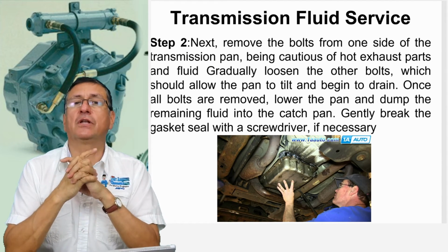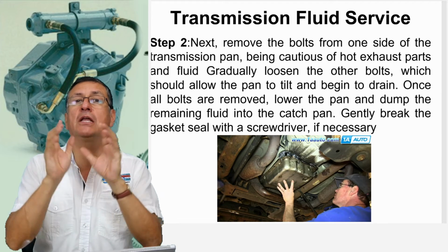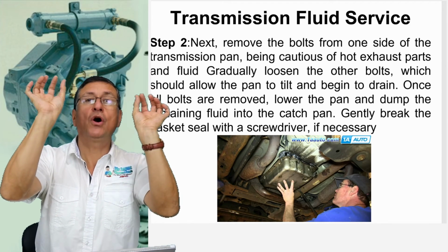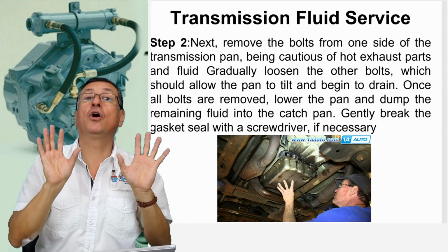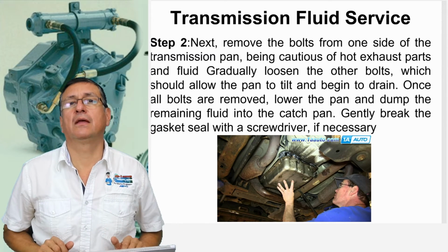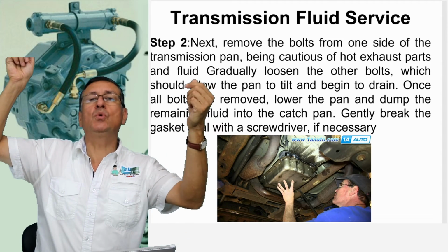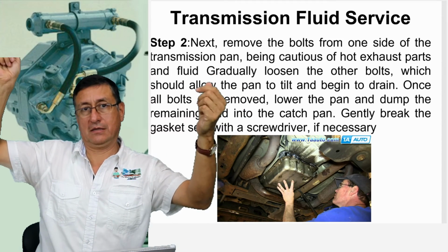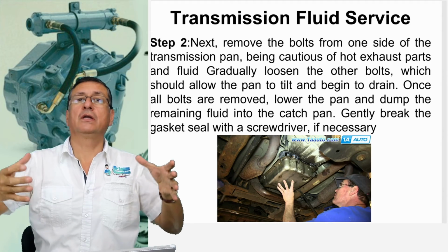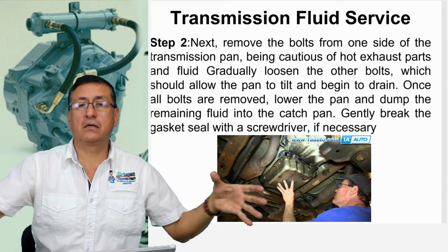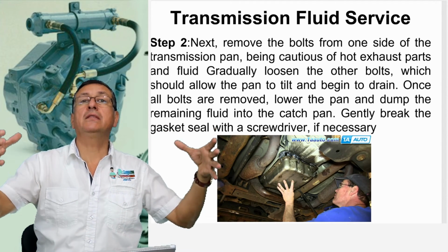Yeah, this is the recommendation. I normally recommend loosening all of the bolts. Only loosen, not remove. And try to keep 2 bolts in place in diagonal. Of course, try to put a container in the bottom to collect the oil.